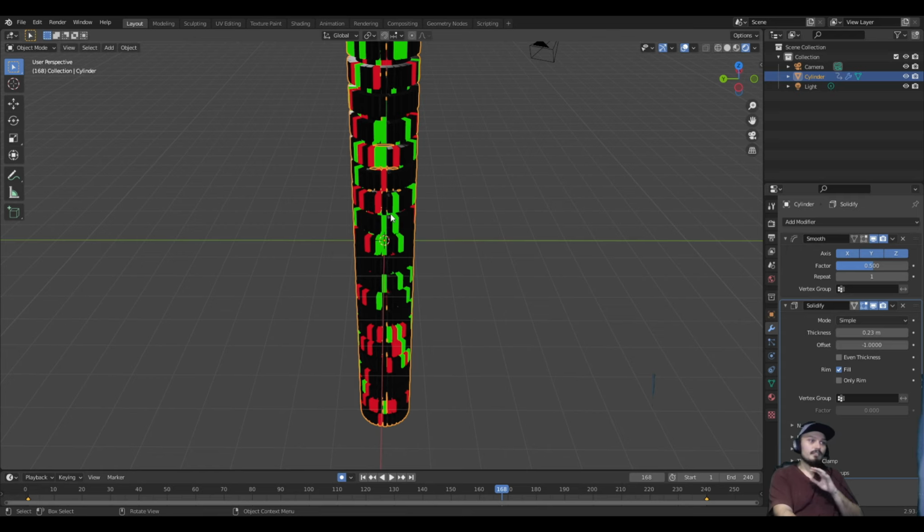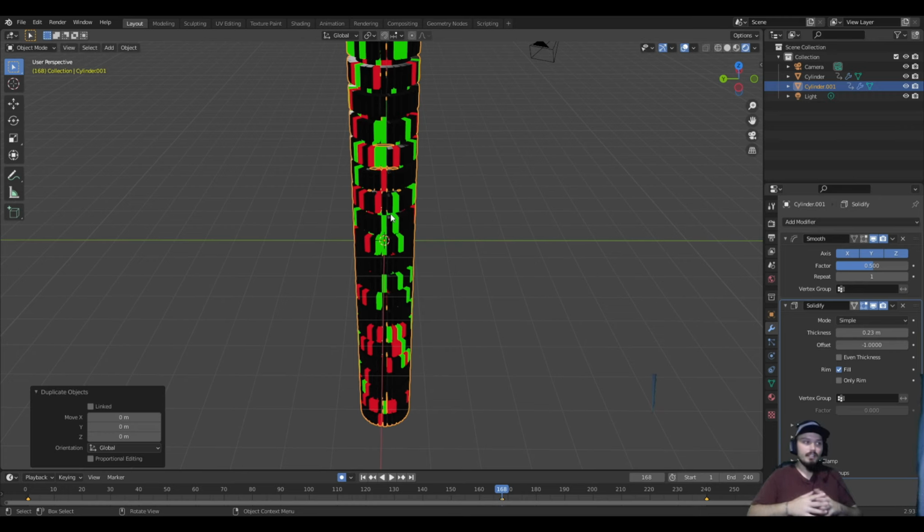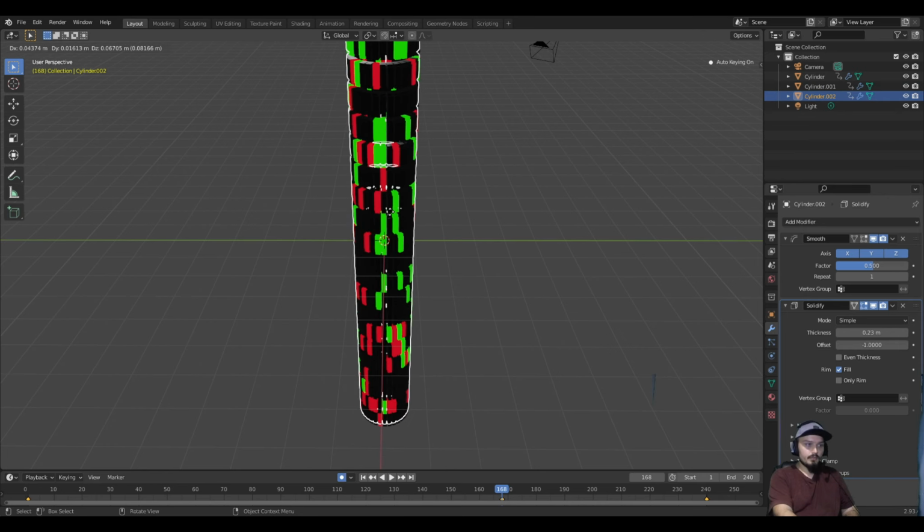So we want to select and hold Shift, press D. Now what that did is that just copied, and now once we do that we hit Enter because we don't want to move it yet, but what that did is that just copied what we already had, right? So Shift D, and then select that there.